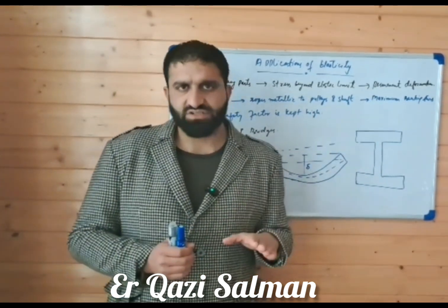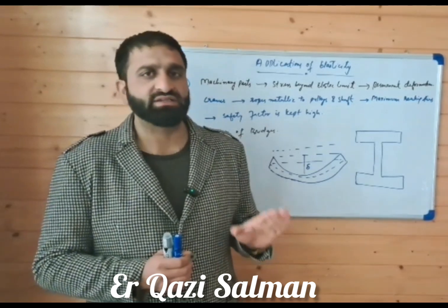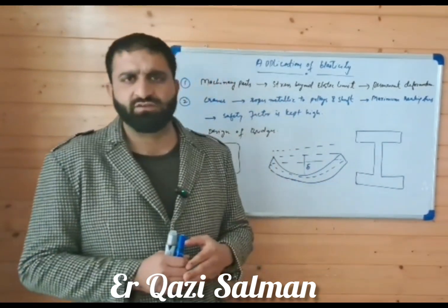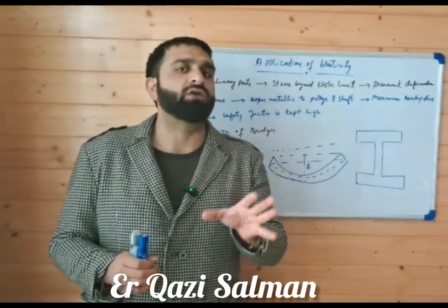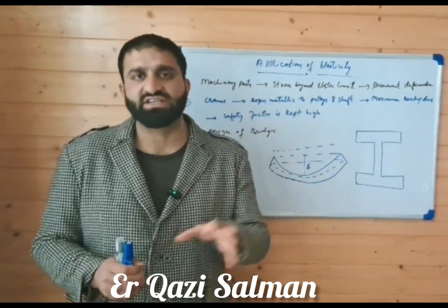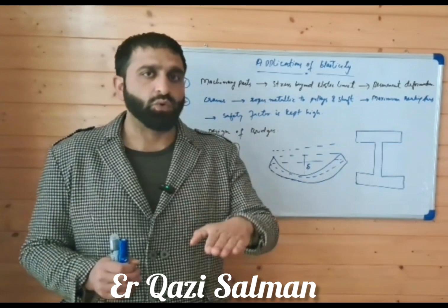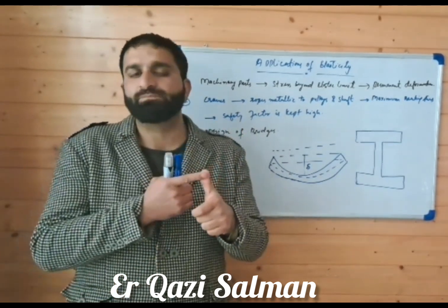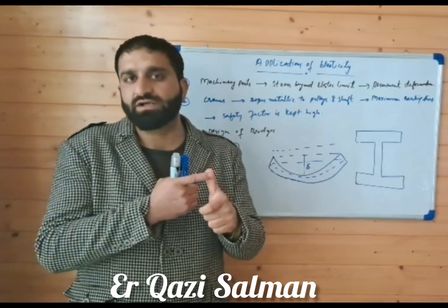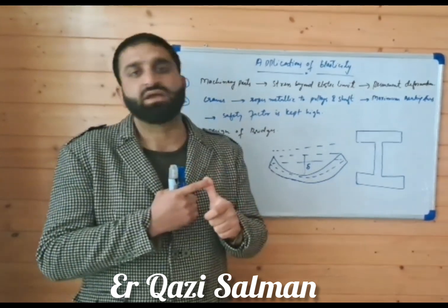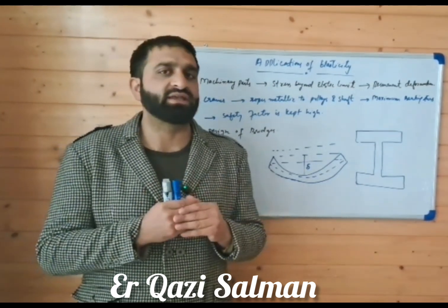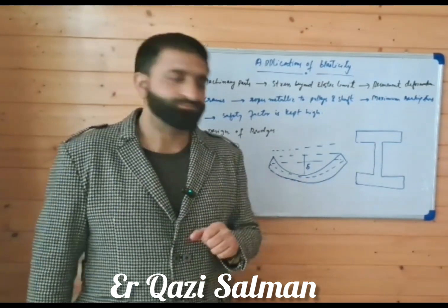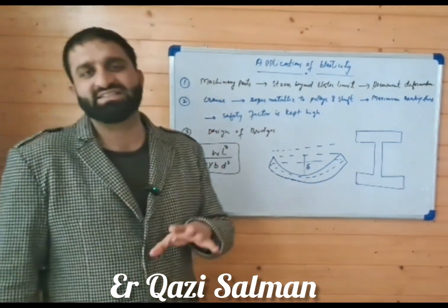That means the working stress should always be lower than the breaking stress, or the safety factor is kept high. As we have already discussed, the safety factor is the ratio of breaking stress to working stress. If the working stress is low, the safety factor is high. So when we use cranes, we should work with a high safety factor, so there is no risk of the rope breaking, which could lead to accidents and even the death of employees. Now, an important one is the design of bridges.